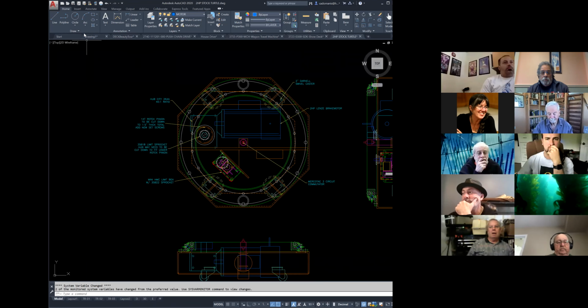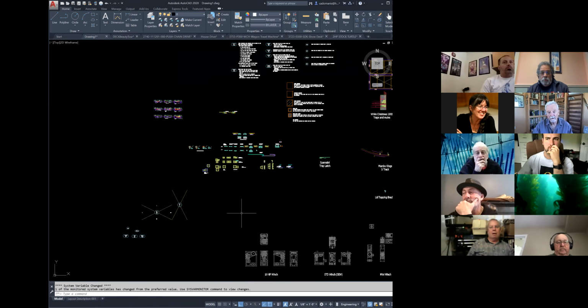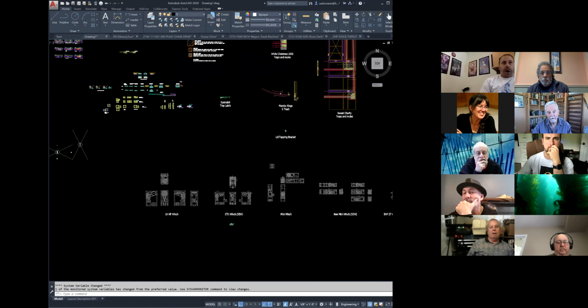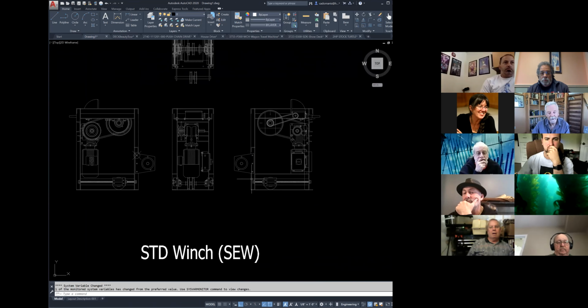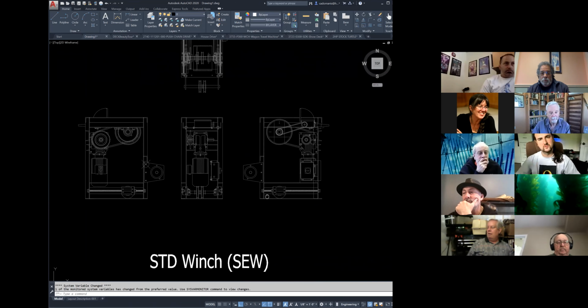So when these pulleys, and generally a bronze bearing in there rather than any special bearing, in fact, it's better to be a bronze bearing, with that outfeed sheave shaft stationary, these pulleys will tend to wind themselves along to line up with the cable that's on the drum. Unless the distance between the drum and the outfeed sheave is longer than the distance to the first deck sheave, or first obstruction.